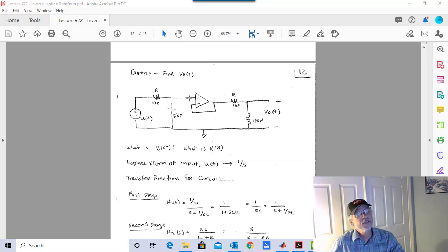So it sniffs this voltage, puts that voltage here, and this has a Thevenin resistance of nothing. So it can put out all the current it needs to make the voltage correct here. Now, a good thing that you could ask is, hey, wait a minute, no current here. How can I get a big current coming out of here? And I said, oh, well, I didn't show you the power supply terminals because we don't do that in EE310. But if we want to make KCL work around the whole op-amp, you've got to show the power terminals.